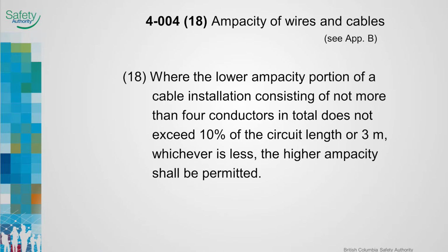Rule 4-004, Subrule 18, can be applied to circuits run above or below ground. The higher ampacity is allowed throughout the run length, provided the lower ampacity length is restricted to 3 meters or 10% of the circuit length.